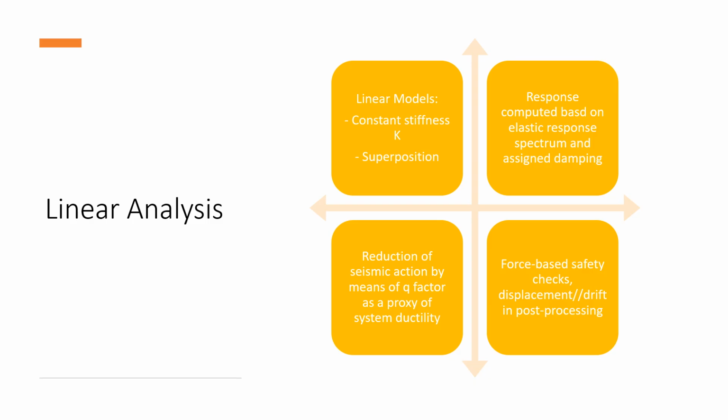And the force-based safety checks establish a framework, allowing in the end to use, in a post-processing procedure, a computation of displacement or drift demand, but they hold on other assumptions that are made in the parameters of the damping or the q factor we have used.